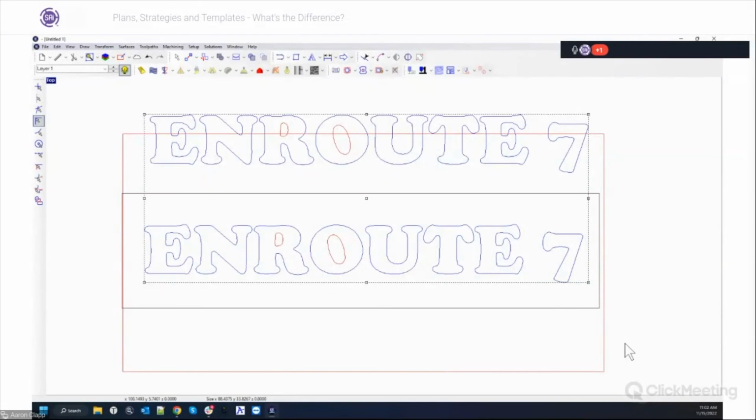I would assume that that's possible. Now, this is probably something I would check with your CNC manufacturer in terms of how reliable that is, or if that's a good idea to do, because EnRoute will output whatever you tell it. So if you are working on half-inch material and the strategy says 1 inch, it will cut past that material and cut into your board a half an inch. So if your machine has the ability to limit the depth and not air out when it sees too much depth, yeah, I can see where that might work.